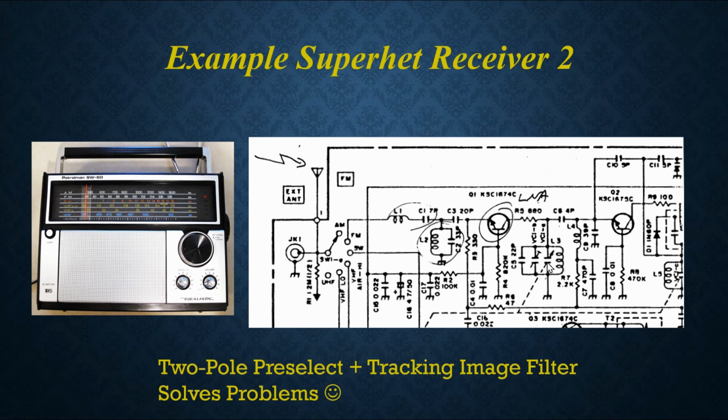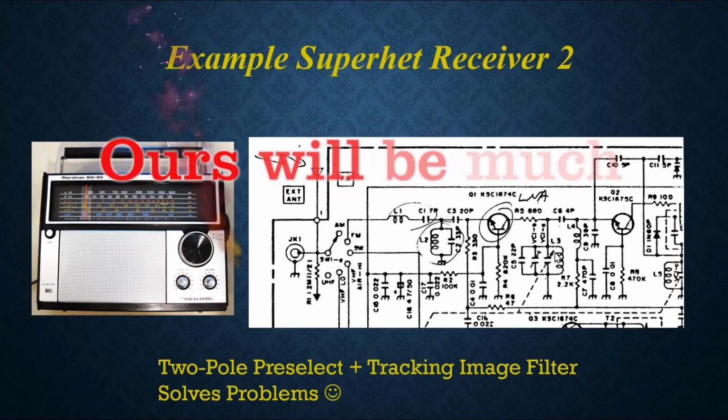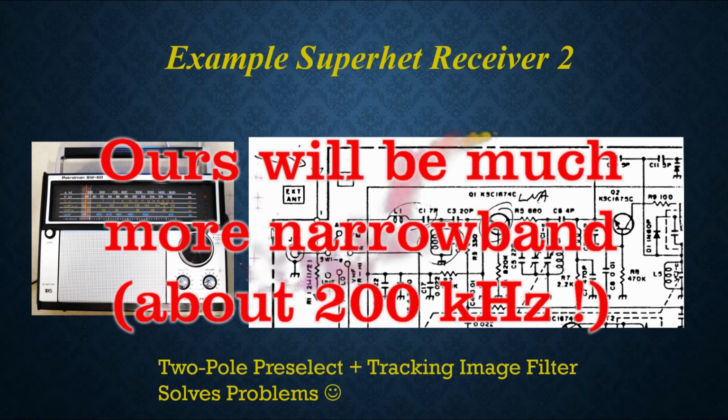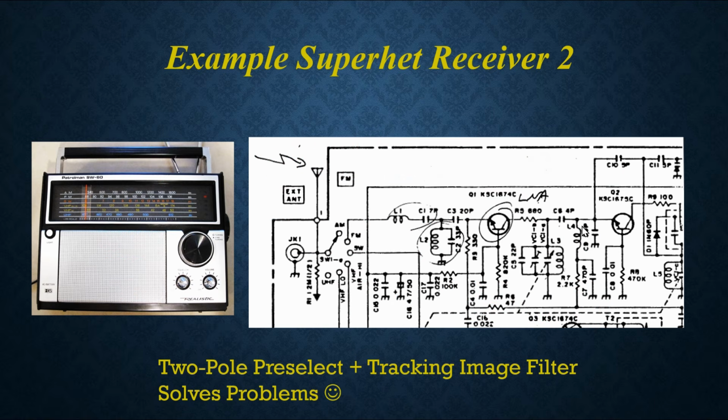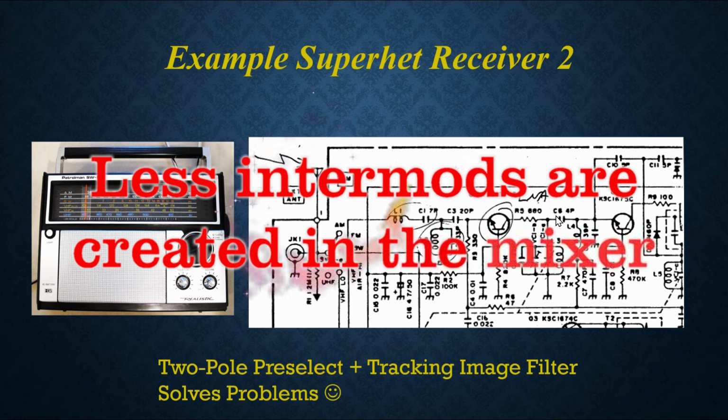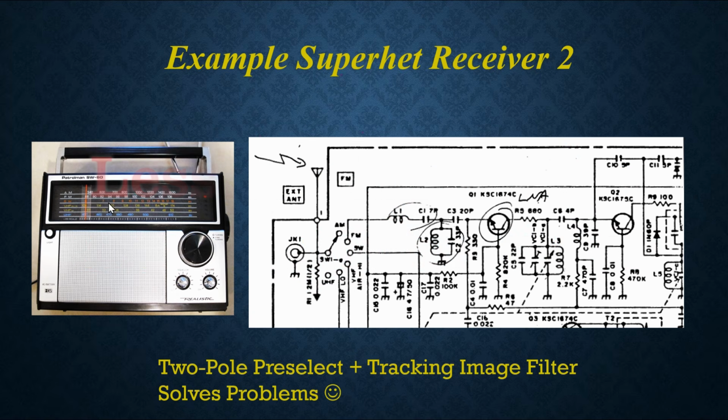And the amplifier accentuates signals in about a 4 megahertz band at frequencies which are determined by this variable capacitor in the tuning, and it tracks the local oscillator. So over here the mixer doesn't get hammered by too many signals. So it improves the performance of this old radio relative to the newer ones.